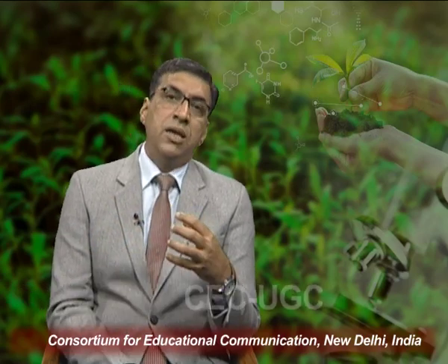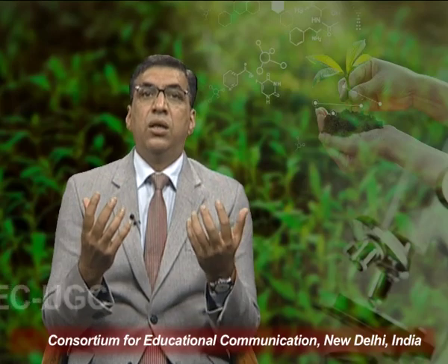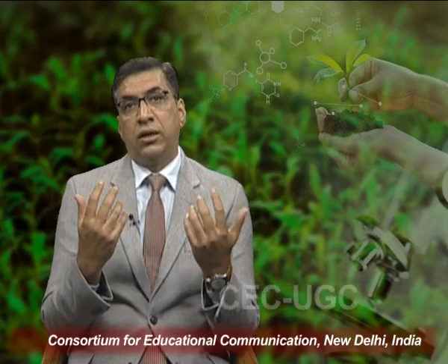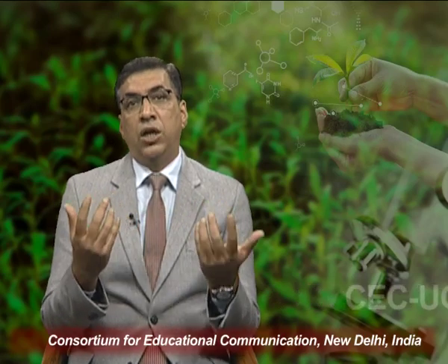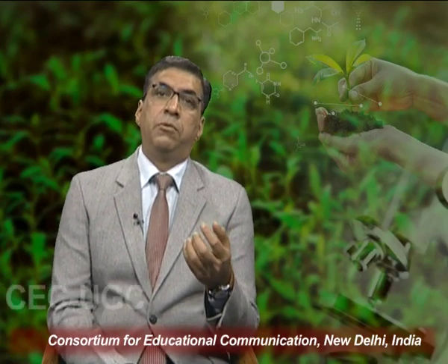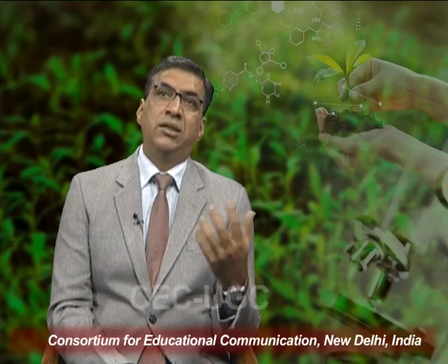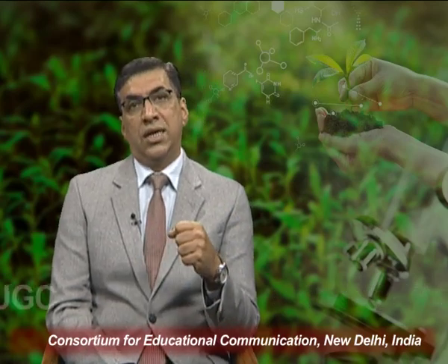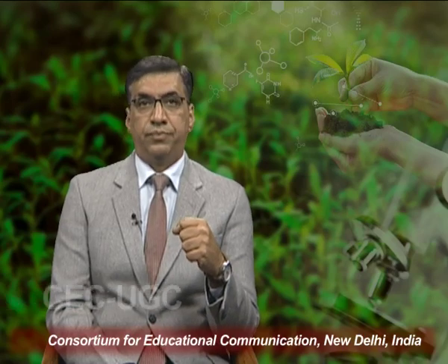And these impellers should cover a large surface area. Therefore, that will allow the transferring of that circulatory effect or circulatory power over the large volume of the bioreactor at a lower impeller tip speed, thereby preventing the excess of shear stress in the culture media and allowing the proper growth of the cells in the hairy root culture.